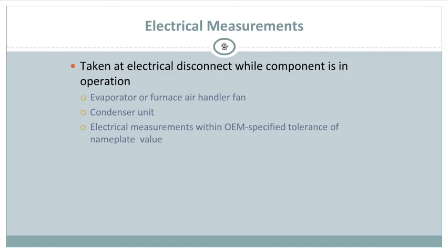Line voltage, again, the line voltage talks about whether it's going to have a separate line coming just to that equipment, or it can be plugged into something that's already there. I just put in these new on-demand hot water heaters in my house. My house is all electric because we live out in the country, and I found out that you had to run whole new wires and double 80 amps into these things.